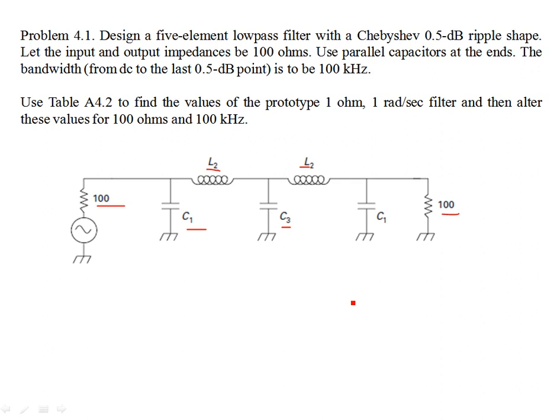It can have a Chebyshev response as well, having ripples in the pass band or in the stop band, if it is type 1 or type 2, or elliptic if it has ripples in both pass band and stop bands. So the response could be based upon any well-known classical analog filters.